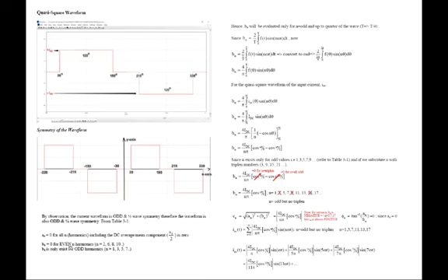bn is 0 for even harmonics, so there will be no coefficient Cn at 2, 4, 6, 8, 10. All the even harmonics will be 0. bn only exists for odd harmonics, which are 1, 3, 5, 7. The possible values of n for this quasi-square waveform are all the odd harmonics. Now we're going to evaluate the Fourier analysis to get the Fourier series equation describing the quasi-square waveform. Hence bn will be evaluated for n odd and up to a quarter of the wave.